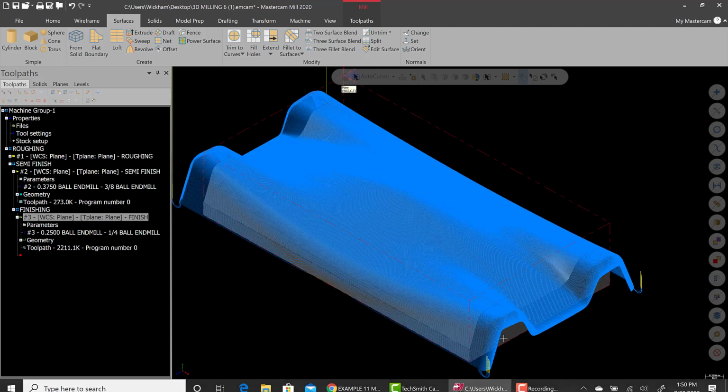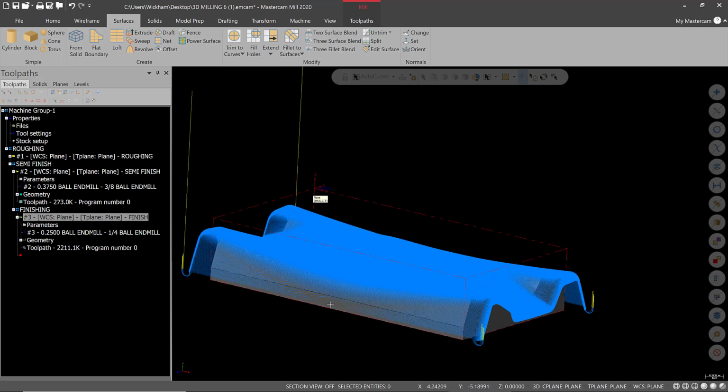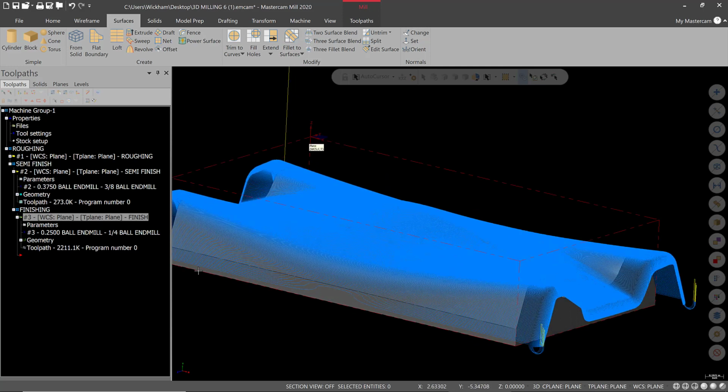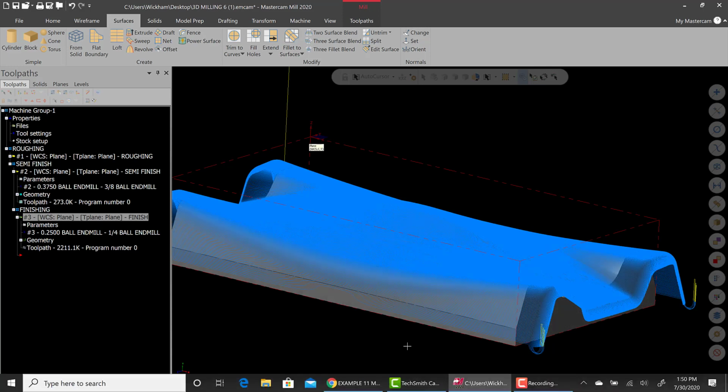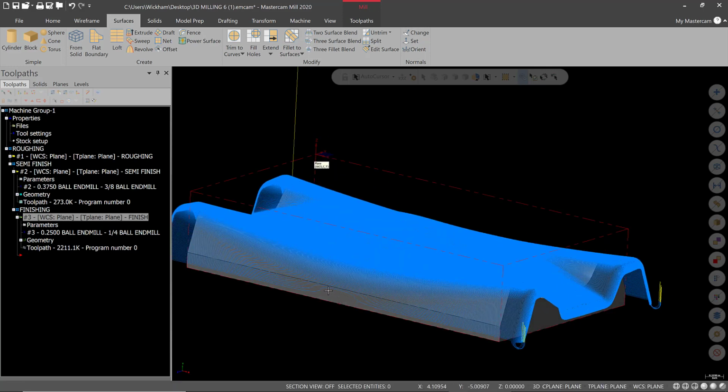Okay, so that's just a little thing in the surfaces, and again, don't panic about the little red here. That's going to happen because there's technically no material there. That wall has already been machined by however we machined the thickness. I think it's 2.5 inches here. So don't worry about that. That'll be a blend. And like I said before, one way you could do is machine all of this in one. That's not a bad idea. Then you could grab it by the flats and face the other side for the second operation. It's not a bad way to go, especially if you're worried about that blend line.